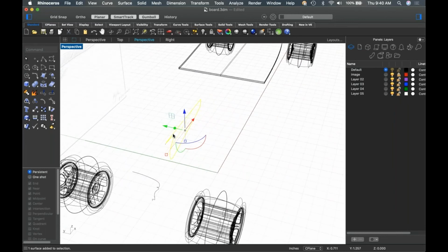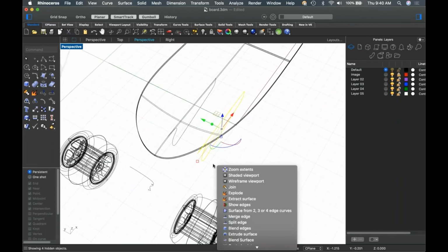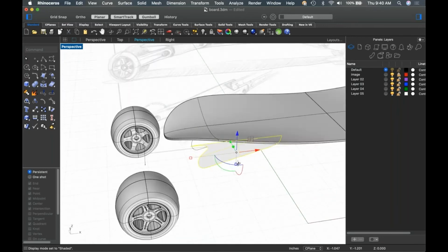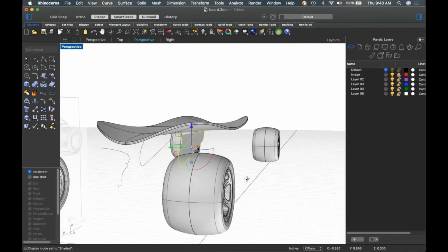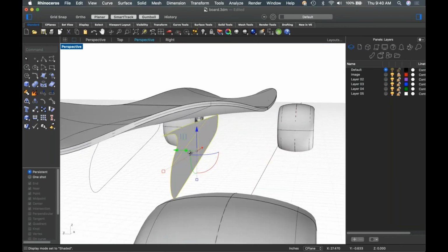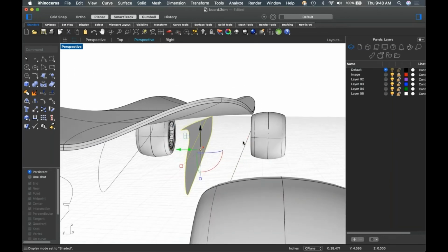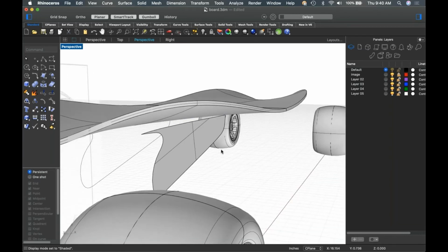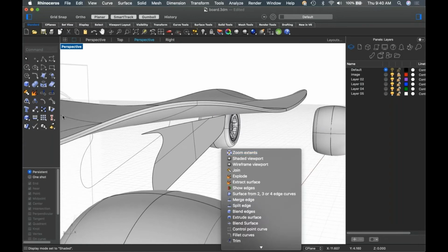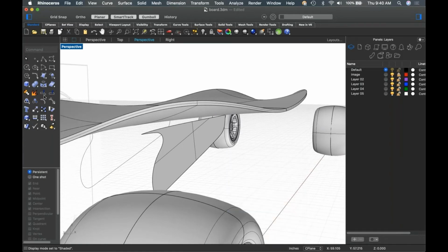All right, so let's place this. Let's bring our board back, and let's place this in shaded view. And I can see right now I've got a problem in the fact that this is way too low. So I'm actually going to untrim, because this is a planar surface, a four-sided surface that's been trimmed. So let's untrim it, but I'm going to keep my trim objects.